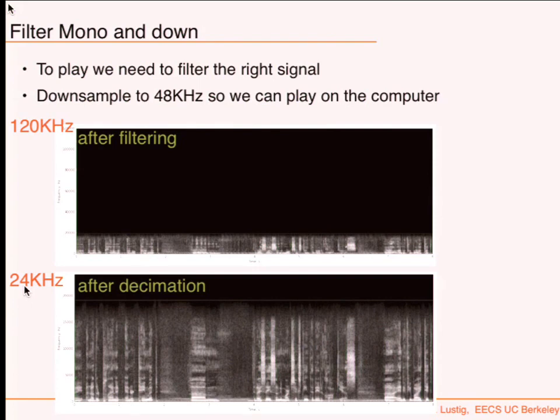After that, if you compute the Fourier transform, you'll see what you have. It stretched the spectrum. Remember what we did: low pass filter, downsample, it stretches the frequency. And then after that you're going to play it.